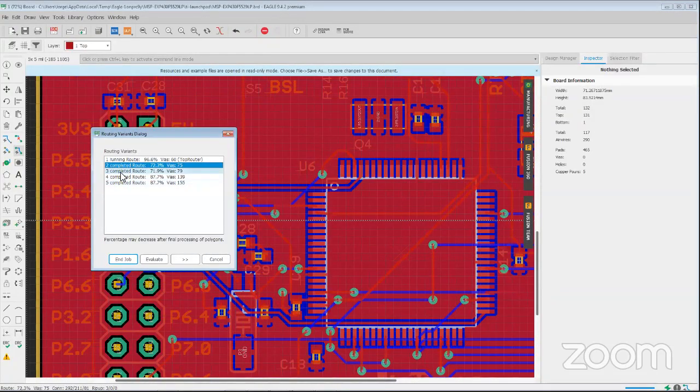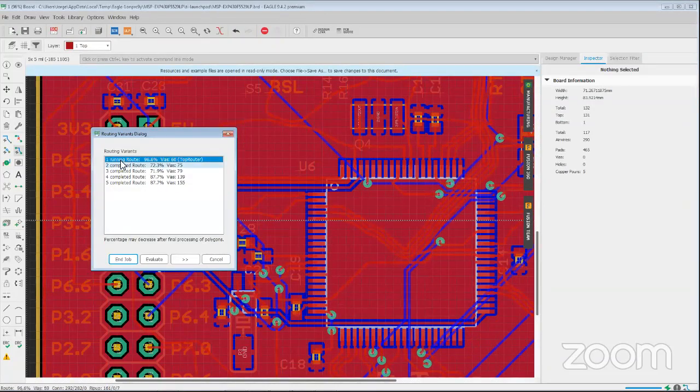Now, while it's running, you want to let the Autorouter run to completion. So if you see it says running, it hasn't completed yet. It's still running, so we want to let it run until completion. In general, it's not a good idea to interrupt it, especially while it's running the top router. You can get Eagle into an indeterminate state. So you want to let it run until it finishes. Doesn't mean Eagle can't recover. Sometimes you can stop a route halfway and it'll be fine, but it's generally not good practice to do that.